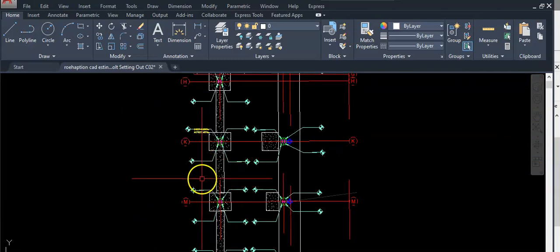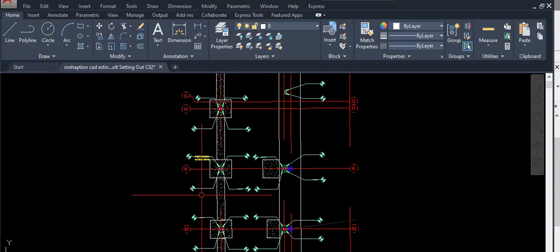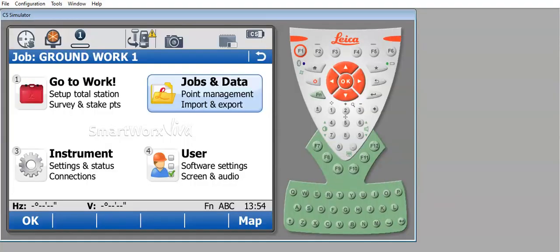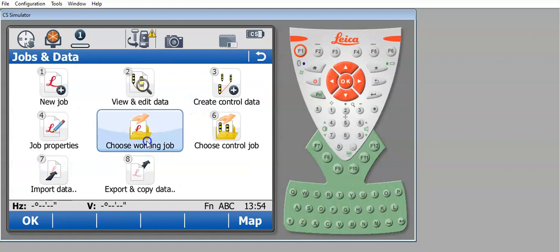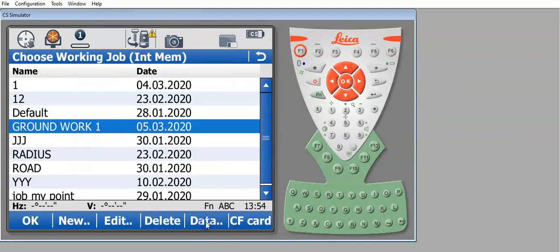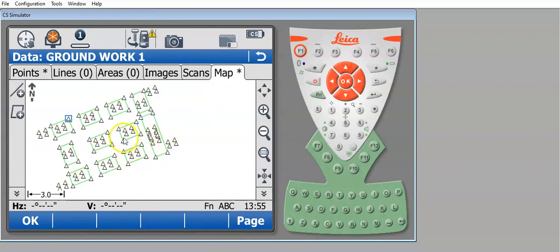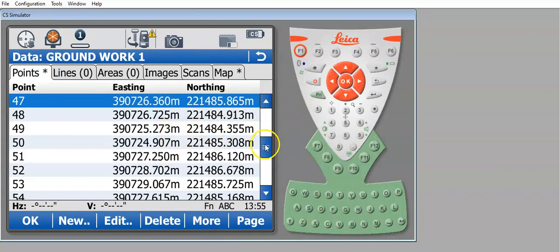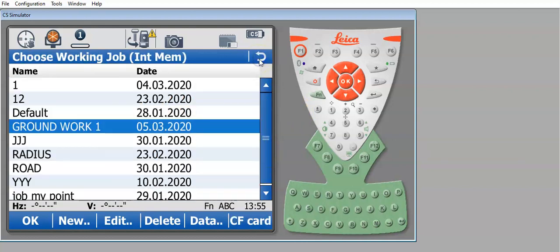and you can set them out on site, whether the traditional way, where you can input them into the total station, or you can do them digitally, like I will show you later on, which is the digital way of using the coordinate system in setting out, where the CAD itself is imported into the machine, and for example you have all these coordinates, you can just pick on them, and basically you will set them out with the total station, the robotic machine.